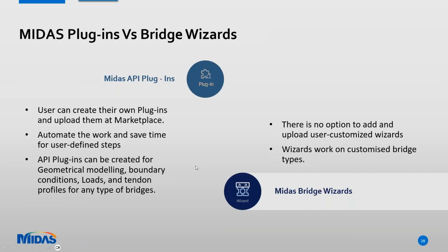Now this is a very important thing because people have doubts related to these plugins and MIDAS wizards. So first I will come to this particular wizard. These MIDAS bridge wizards are nothing but, if you open this structure wizard, some customized templates available in the software, and only for some specific types of bridges. So let's say the cable stayed bridge wizard. In cable stayed, I can generate the 2D structure with the cable arrangement.